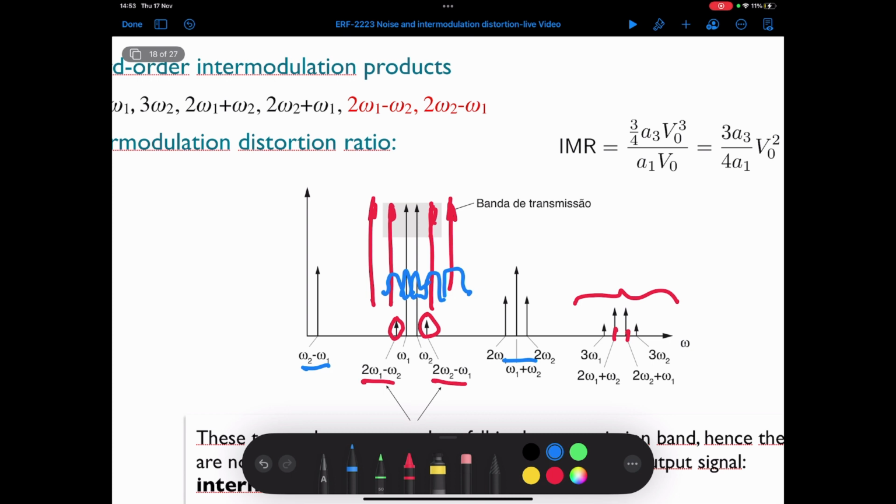And what happens is that, for example, for these two signals, the intermodulation distortion generated by the amplifier from just these two signals falls within the adjacent TV channel. And it's not possible to remove this distortion, right? Because it's a type of intermodulation distortion that falls within the adjacent channel. And so it's like noise that falls on top of the signal, and it deteriorates the performance of the system and reduces the signal-to-noise ratio. Okay.